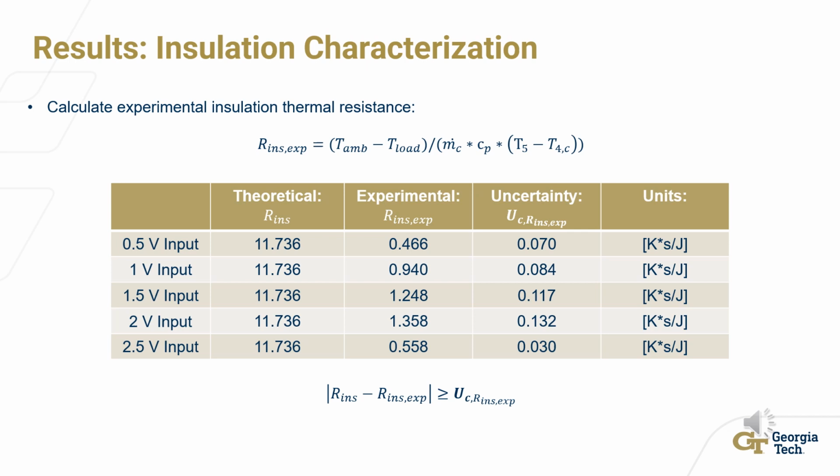Additionally, the experimental insulation thermal resistances do not match with one another from one trial to another. This indicates that unmodeled factors could be affecting the system, such as other forms of heat transfer including radiation and convection, and that the capabilities of the sensors to measure the necessary physical quantities for the calculations is not accurate enough to allow for a proper quantification of the system parameters. Assumptions such as treating air as an ideal gas and using constant specific heat for this substance can also have unaccounted for impacts that can be leading to the deviations in the results.